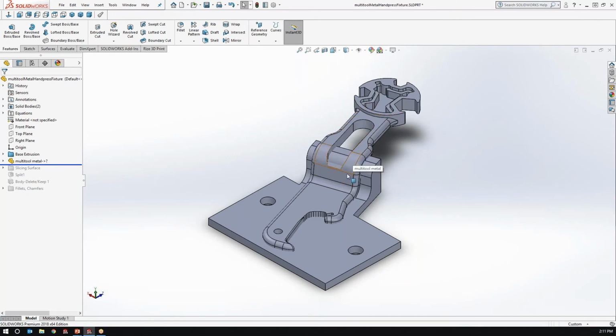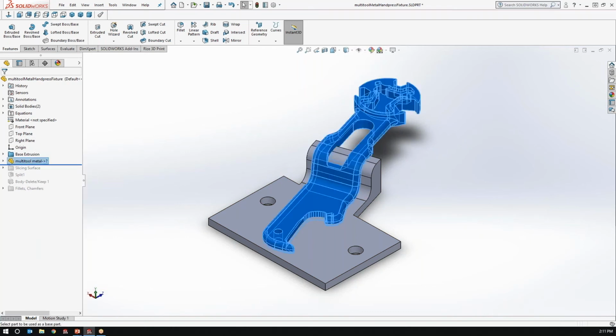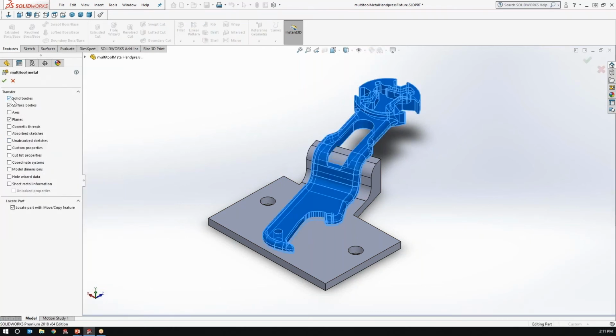Once you open the part, then you'll have the opportunity to mate it to different parts of the part that is already imported. So I'll show quickly. When it first comes in, you will see this list of options. So you want to make sure that this check mark is checked.